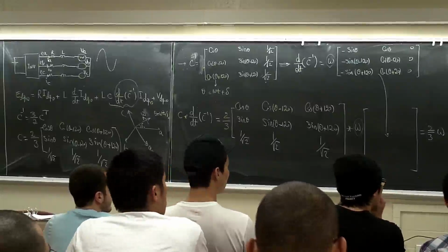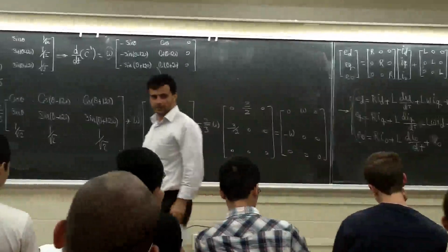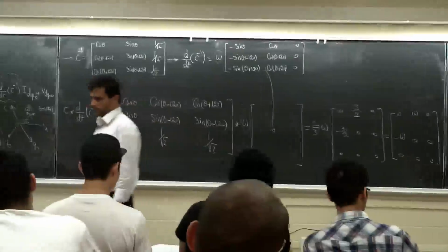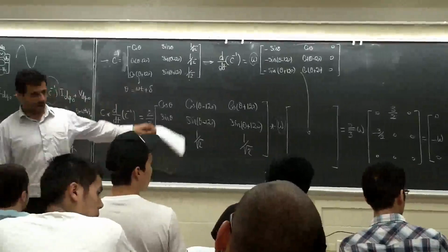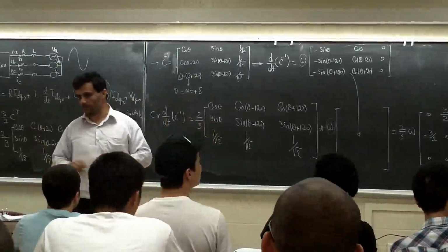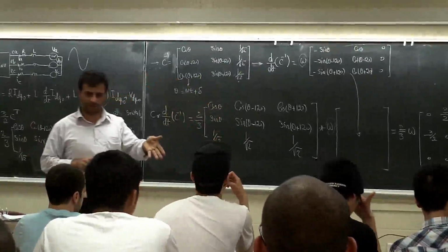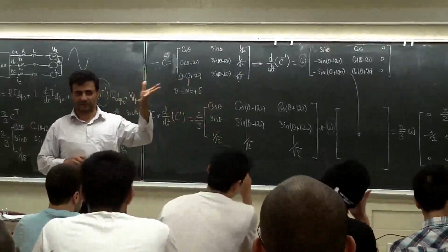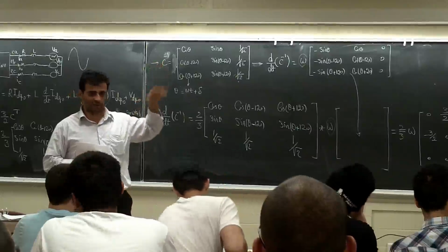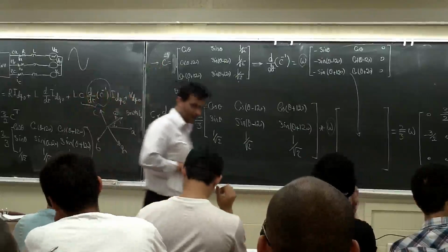When you had circuit theory, which one was easier to deal with? DC circuits or the AC circuits? DC circuit was easy to deal with, right? So the calculation was much more straightforward. You didn't have an omega term, you didn't have those kind of things. You go, you calculate it. You have transient, because of L or C in your circuit. But if it is a steady state, you can say L is short circuit, capacitor is open circuit, it's just like a resistive loop. You deal with that like that, right?